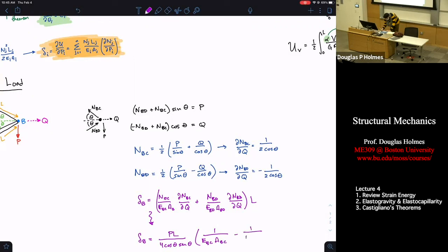And in the deflection, our fictitious load doesn't appear. And as a sanity check, we know that if the cross-sectional areas, E and A, were the same, there would be no horizontal displacement. These two terms would go to 0. Our horizontal displacement would go to 0. Sanity check. I rushed here.